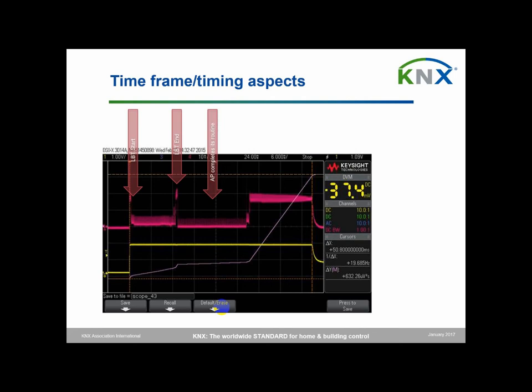And this will take a little bit of time as well in order to retrieve it, in order to make it ready for sending. The sending will then take place here, so it will then transmit the precompiled frame that has been retrieved, that has been set up. And the actual sending, of course, means that more energy will be consumed. That is what we see here in the purple curve. So here the energy consumption is moderate.